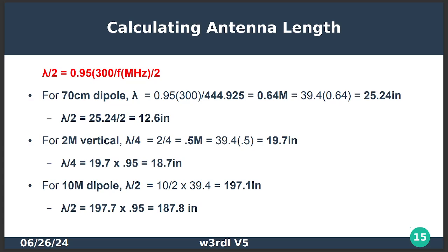So that's your quarter wavelength, and then you multiply it with your factor. I don't honestly know what the factor is for aluminum, and I also don't know what the factor is for aluminum that's got splotches of paint on it. That's probably different. And we've had discussions about the diameter before, and we haven't been able to pinpoint why, but it does matter. Anyway, when you take your factor for bare copper, 0.95, it becomes 18.7 inches.